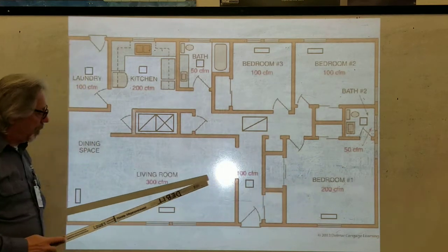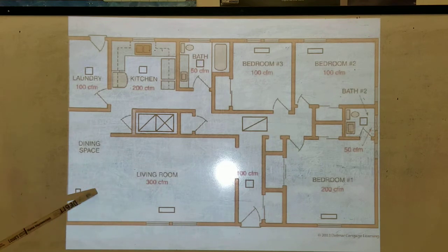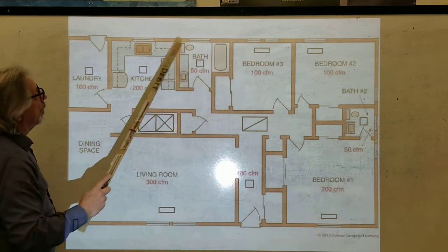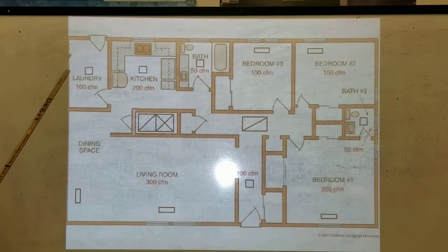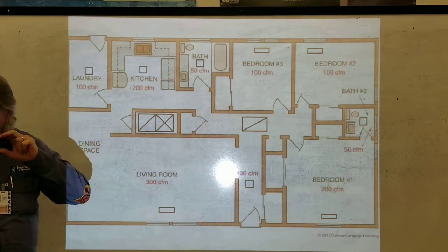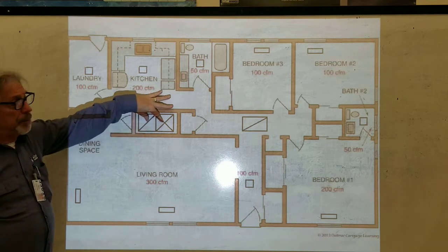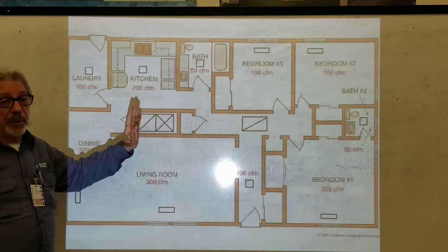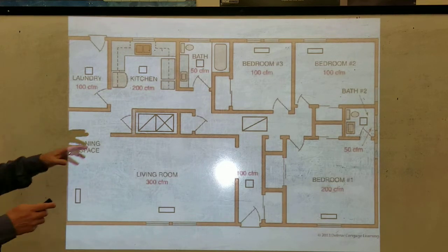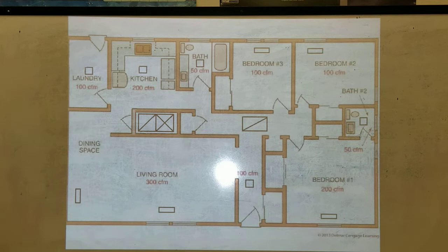Each one of these is a supply air register. I know they don't have X's in them, but they're supplies. First thing we do is lay out the ducts. You've got three sides of this plenum that you can use. If these two plenums are together, you're not going to get in between them to tap in a start collar for ductwork, right? So you've actually only got three sides. Think about that.